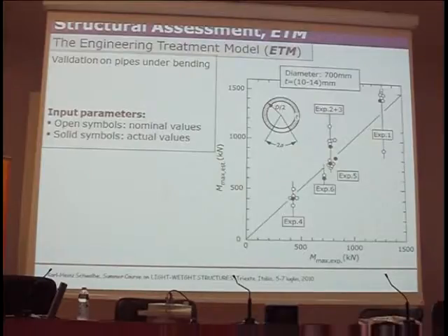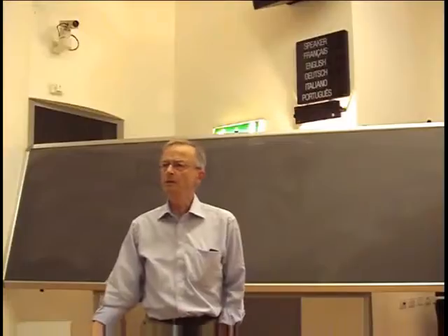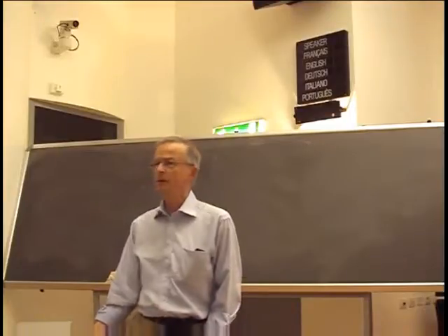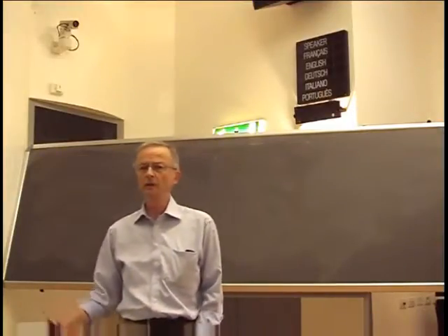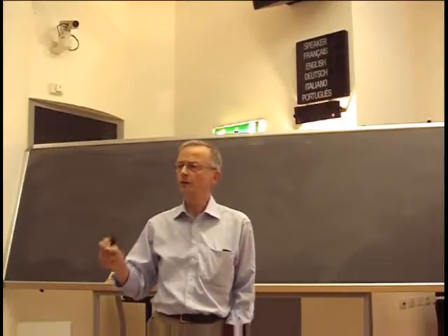Okay, you see, there is substantial difference here. And remember what I said on Monday, I think it was Monday or yesterday, whenever you have to do a failure analysis, look at the broken parts. Don't believe what people put on your desk. I mean, there are many cases where you have to believe. You can't go to an offshore platform and measure the thickness of whatever it is. But you have to be extremely careful, otherwise you can come to false conclusions.